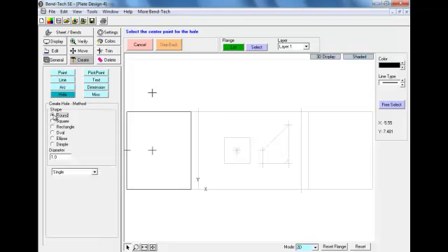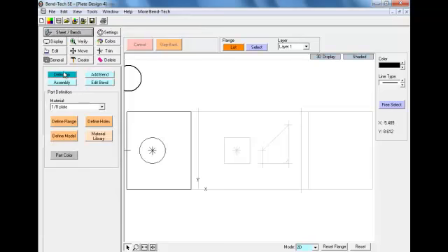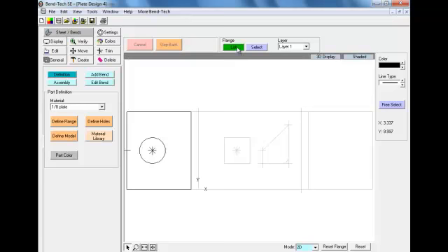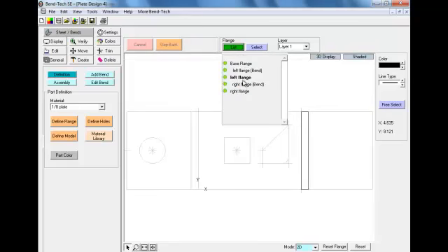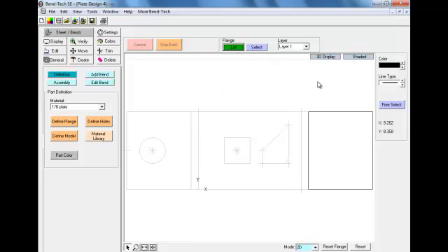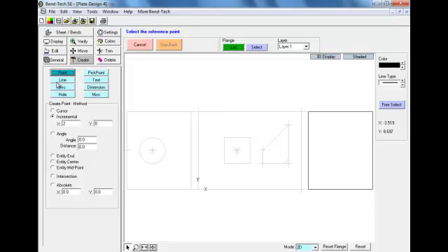We'll select that point, and then our hole is going to be 2 inches to the right of that point. Selecting the point we created on Entity Center, we can now place that point. We can then fill in that with a hole. We want a bigger hole on this, so we're going to use a 2-inch diameter, placing on that point. Once that hole is created, we can define it. And that flange is now created.